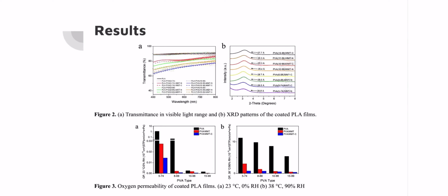Coatings with PVA are nearly as transparent as PLA regardless of molecular weight. A slight reduction in optical quality can be observed with PVA 15 to 99. This reduction of optical quality continues as montmorillonite is added in a 50-50 ratio with the PVA binder. The interlayer distances in X-ray diffraction results also suggest that montmorillonite undergoes co-assembly to align to one another while being subjected to shearing stress during the coating process.